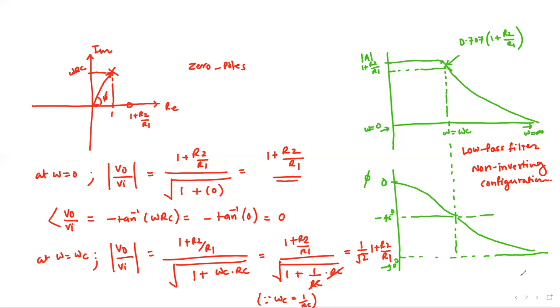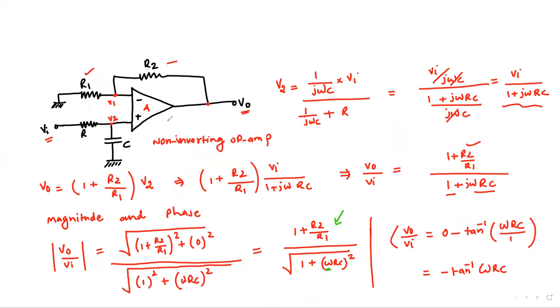Right. So we can compare the two cases where we use the op-amp as an inverting amplifier. Inverting amplifier in the sense we had this configuration where the positive terminal is grounded and we connect the capacitor in the feedback, and the resistors R2 and R1 are there as before, which set the gain, and the capacitor is added extra.